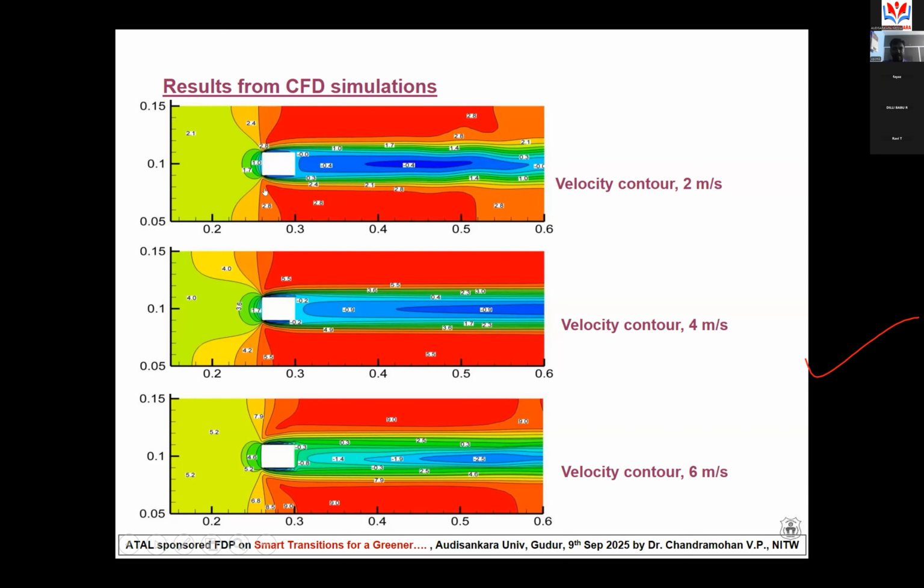And then you can see when the air reaches the surface, the inlet surface. Let us assume this is the inlet surface and this is the outlet surface. When the air reaches and hits the inlet surface, the velocity there will be around 1 meter per second. But just behind the object, you can see the velocity is almost 0 meter per second, or sometimes negative velocity. When the air flows over the object, wherever it hits hardly, those places will have velocity. A wake will be formed just over the object. That's why somewhere the negative velocity is found.